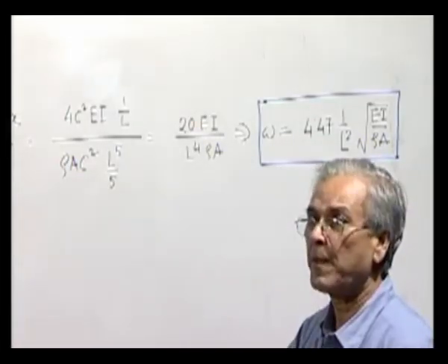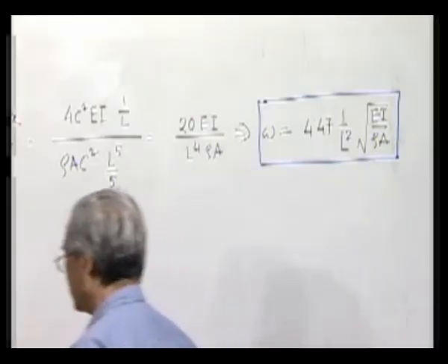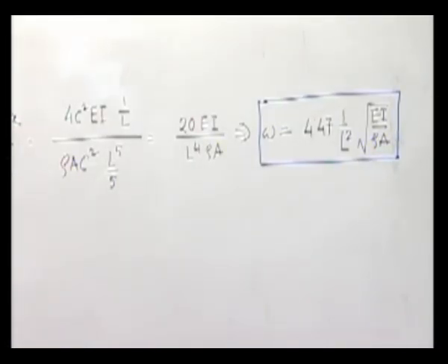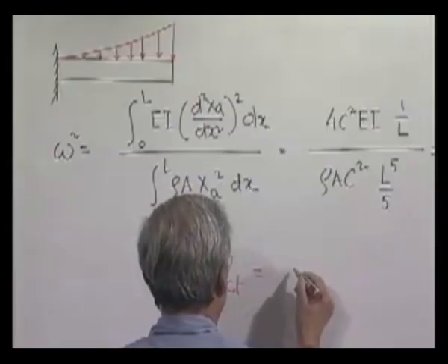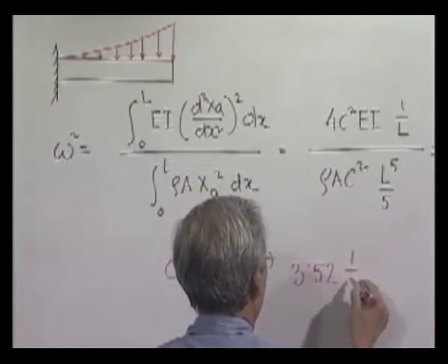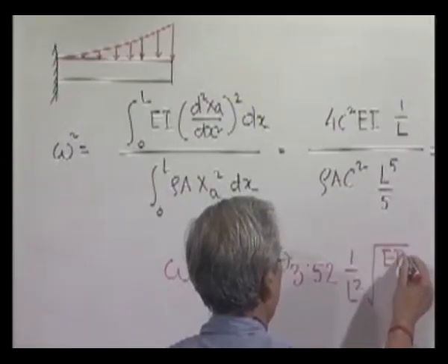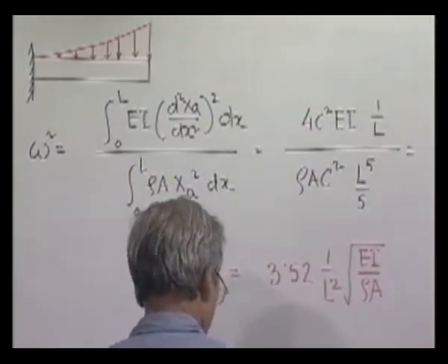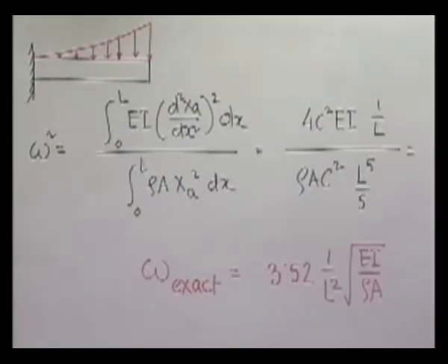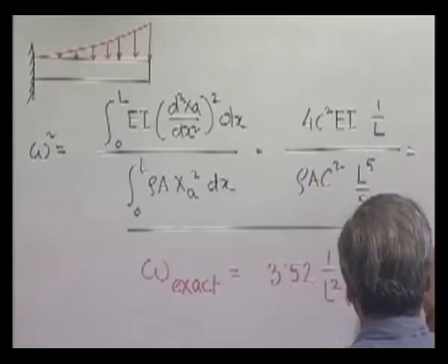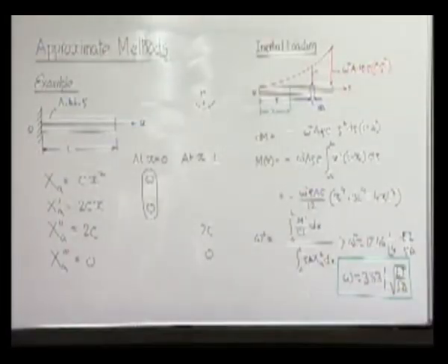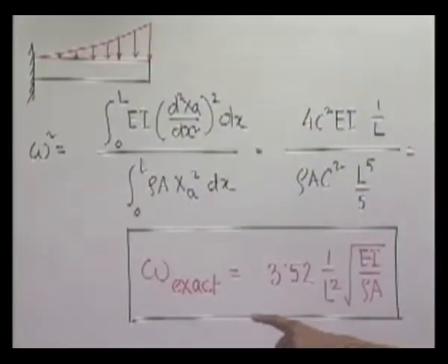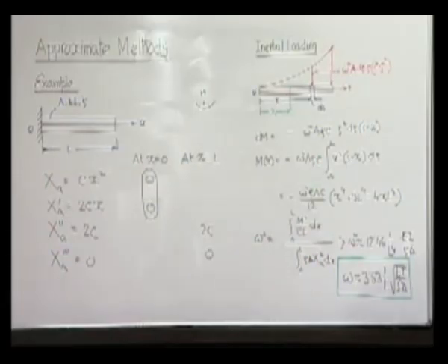And for a cantilever beam, we have already solved by exact method, and the exact value we already calculated earlier, which was equal to... now if we compare, this is the exact, and using this simple straightforward assumption about the displacement function Cx², the Rayleigh's principle gives this, and using the same assumption, if we use the modification proposed by Grammel, we get this.